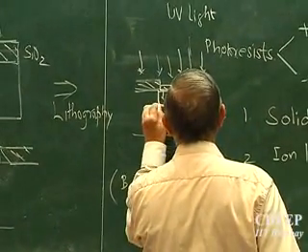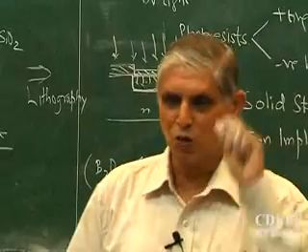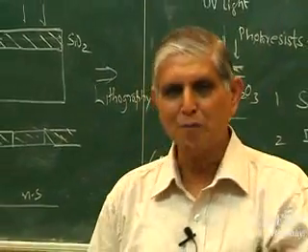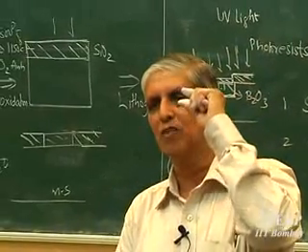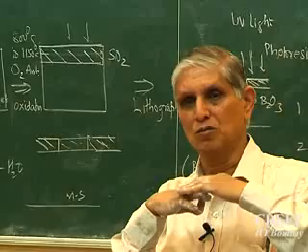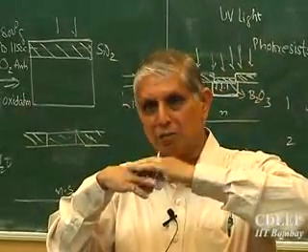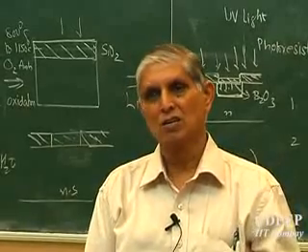Now a question was asked last time also: how many impurities do I need? Let's say I want the same concentration of P as of N. So how many impurities should I add per cc? Twice, because it should first compensate. Is that correct? However, this is interesting: where is the junction? What is the concentration at this point? Zero. So at the junction we have zero net concentration, P and N are fully compensated. That's the place where P and N are fully compensated. It's called the junction. That word junction comes because of that. The net concentration there is zero, because otherwise N cannot start. So at that point P and N must balance, so that the junction is created.